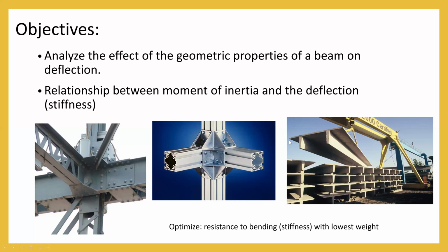Like parking garages use these double T beams. Parking garages almost need to be heavy because the self-weight helps with the structural stiffness of them, as the cars are all, the dynamic loading from the cars and stuff. So they use these double T beams like here. But then depending on other situations, you can have different shapes, some weird funky looking shapes like this aluminum, and then of course our steel. So for this week, we're just going to look at 2 shapes, and we're keeping the material the same. And again, we're going to see how just changing the shape changes the moment, or changes the stiffness.